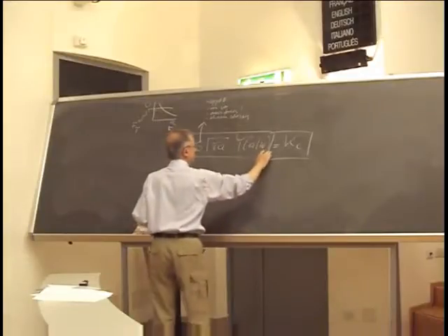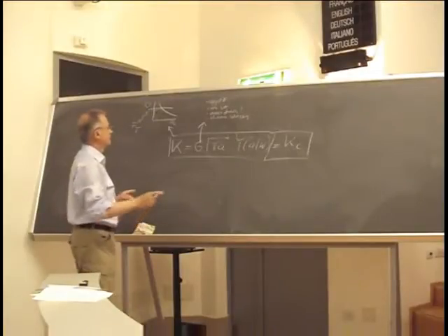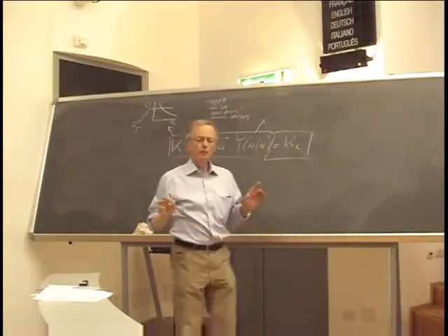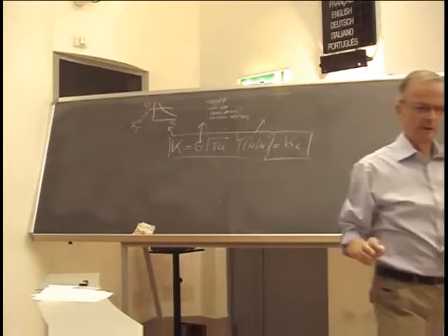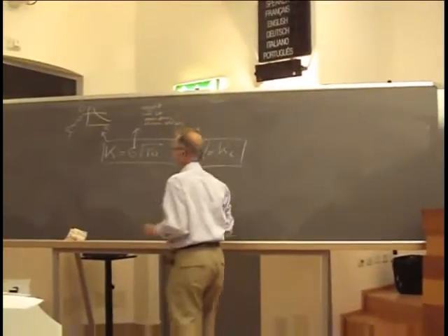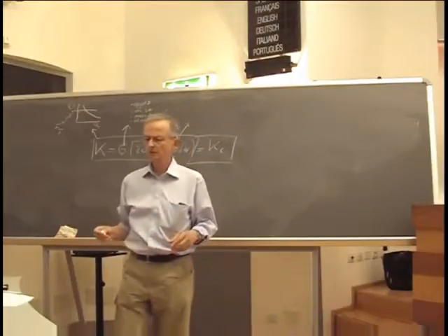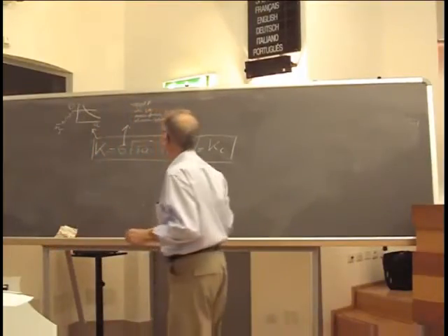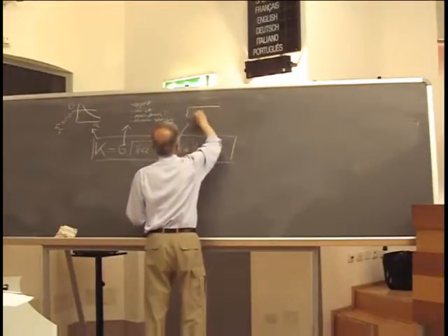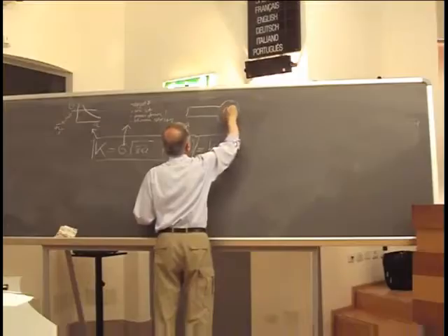The failure condition is given by the equality with the critical stress intensity factor or fracture toughness. Then Y of a over W. We have to know where the crack is going to start. I remember experiments done by the predecessor of EADS when they designed what was then the Eurofighter. They had a tensile member and a bolt here.